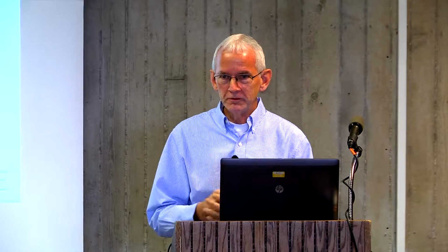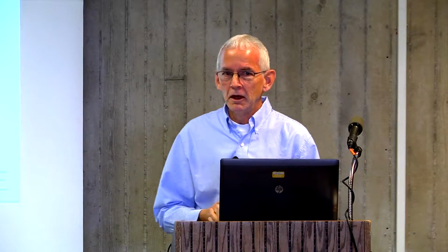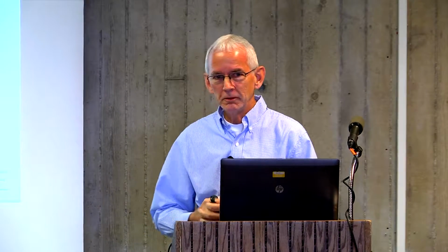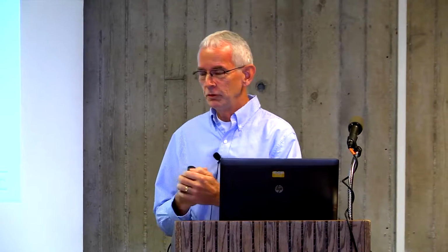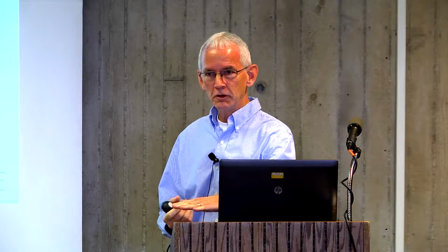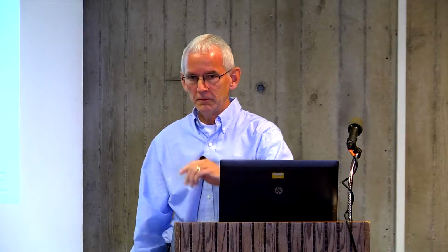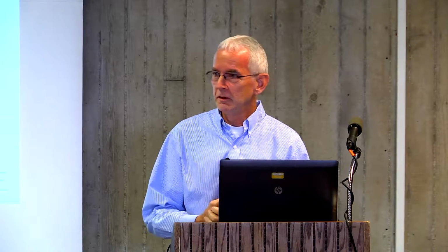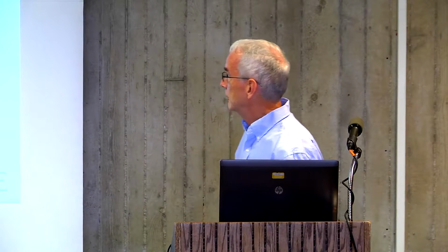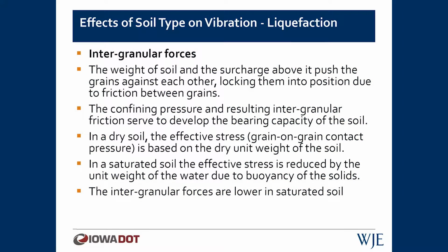Some of the basics of geotechnical engineering is the concept that the deeper the soil is, the more confinement it has, the greater is its bearing capacity. If you uncover the soil from a point in the ground, you lose the surcharge, you lose the confinement of the soil, and therefore its bearing capacity goes down. It's based on the confinement and intergranular forces that are holding the material together. The confining pressure and the resulting intergranular friction serve to develop the bearing capacity of the soil.